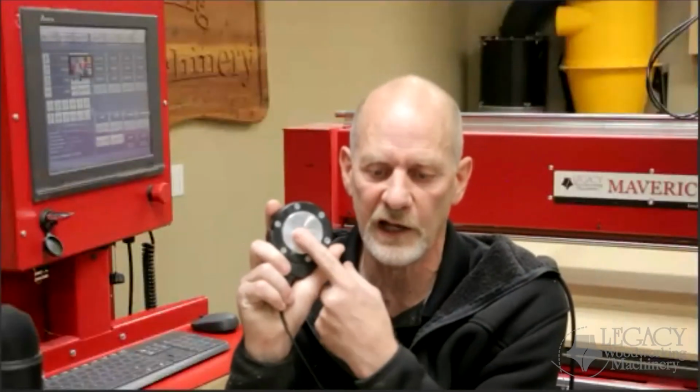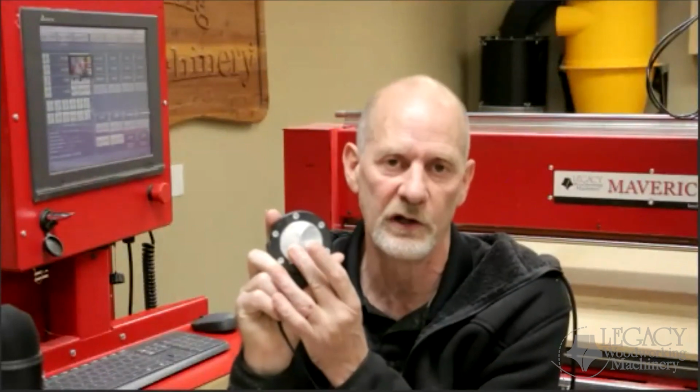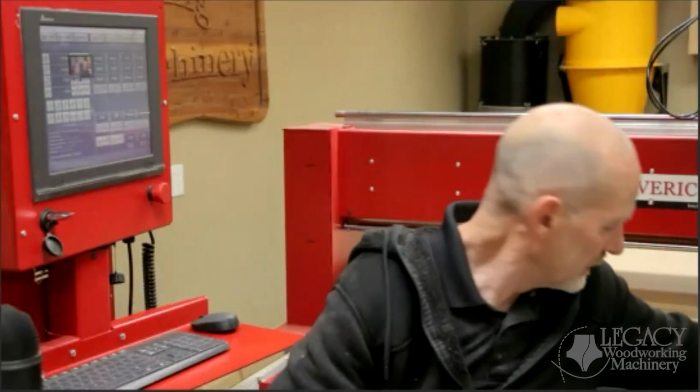Or if this got crashed and all chewed up and you ever had to replace this pad here, I would redo the calibration on it just to make sure that everything's perfect. Okay, it might be a few thousandths difference, but I'd still do it. Right, so if you have to adjust just this plate, or you have to replace your Smart Tool because it failed or got ran over by a truck or something like that, then you're going to replace it and recalibrate.